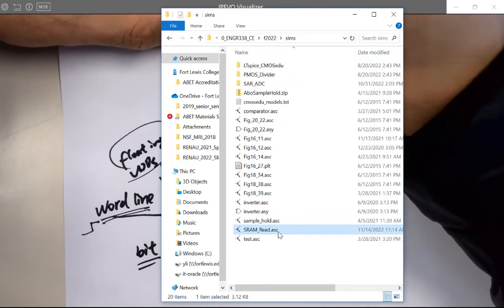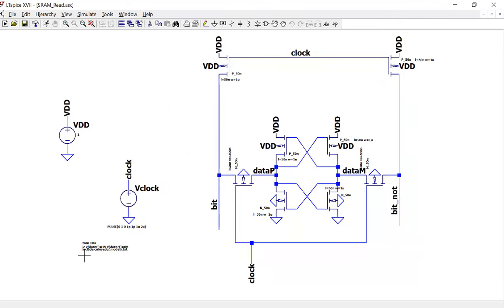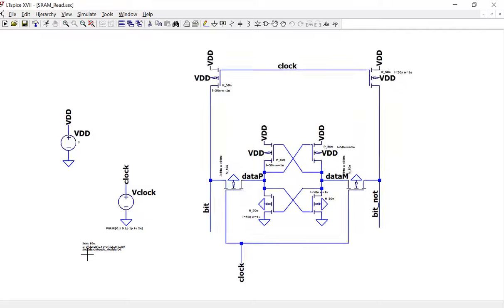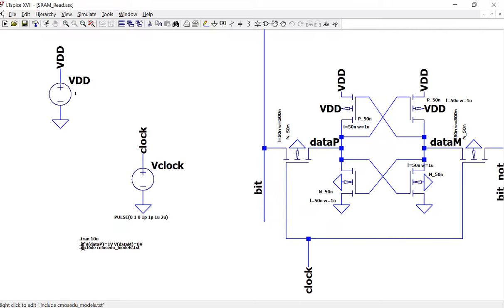You can Google how to assign an initial value in LTspice. But I'm showing you here, it's recorded. I'm showing you here, see? No. .ic, initial condition, .ic, and then V, capitalize the V, parentheses, and then the node.